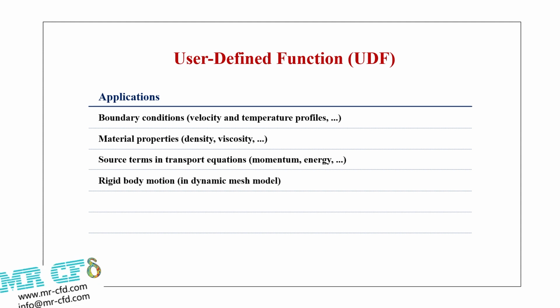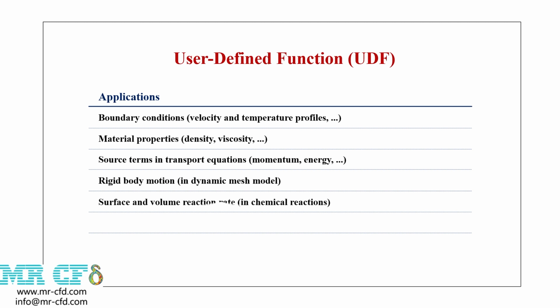Using UDFs to define the motion of rigid bodies in dynamic mesh models. Using UDFs to define the surface rate and volumetric rate of chemical reactions in the equations of chemical processes. Using UDFs to create source terms in user-defined scalar transport equations, and many other cases.